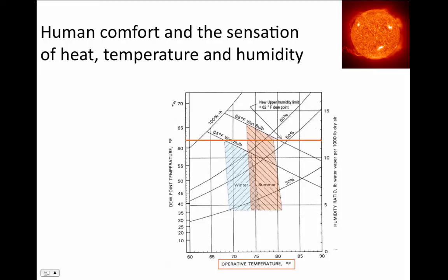They took a naked person, put them in a room that they could control the surfaces of and could control the air temperature. So they took that naked person and made the surfaces of the room 85 degrees, but they made the air temperature 40 degrees. And the person was perfectly comfortable because their body was radiating energy to warm surfaces in that room.